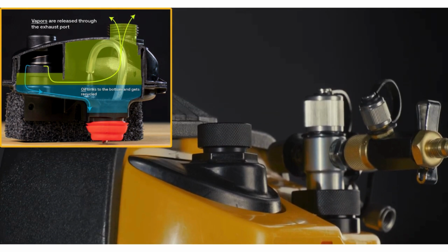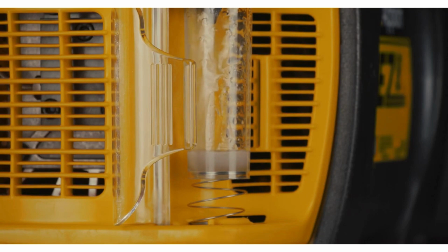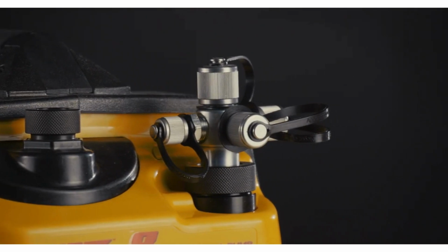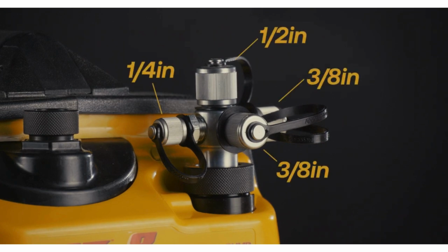This vacuum pump features a 2-stage exhaust system with advanced anti-suckback technology that eliminates check valves and other flow restrictions, further accelerating the rate of evacuation. The adjustable multi-port input increases flow up to 32 times when compared to single-port pumps. This multi-port input features one 1/2-inch port, two 3/8-inch ports, and one 1/4-inch port.